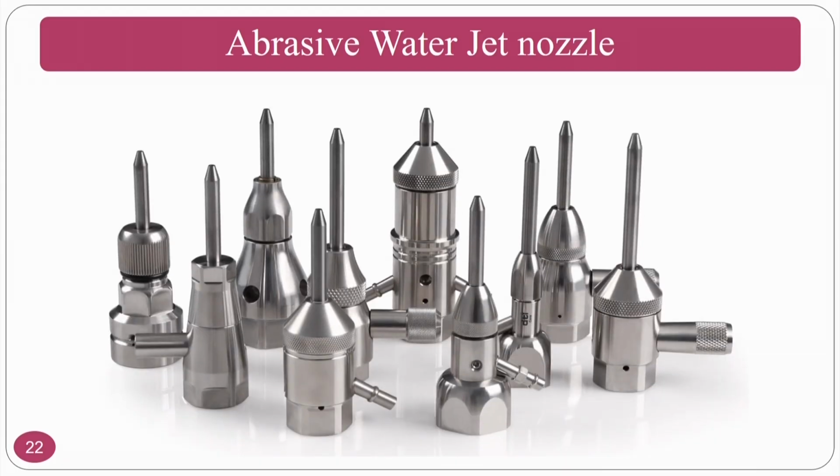These are the other varieties of nozzles where you can play with the stand-off distance. The stand-off distances are varied. If you go for small nozzles, it will be different. In this particular nozzle, this is how the abrasives are fed. In some cases the abrasives are fed here, in some cases you can feed perpendicularly. So, how you want, you can feed. There are multiple jets; you can have multiple abrasive jets and a water jet. So, this is how you can play, depending on your application, whether you want to go perpendicularly or at a certain angle. Optimization of this may also be a good study. How to feed? Assume that my water is coming like this. At what angle should I feed my abrasives?